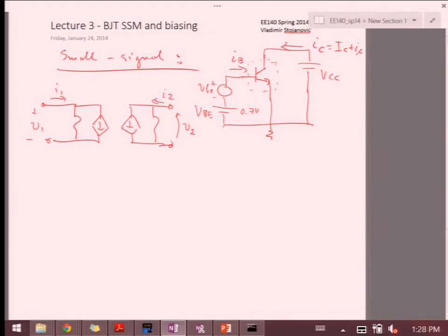By the way, I'm writing voltages as plus minus V1. Then sometimes I get lazy, so it becomes just an arrow. Okay? And the head of the arrow means plus. So if you see that, don't be confused. That's not current flowing. That's just an arrow pointing from low potential to high potential in the circuit. Okay? And now we can name these conductances as 1 over Y11 and 1 over Y22. And then I'll write this guy as Y12 V2. And then this will be Y21 V1.